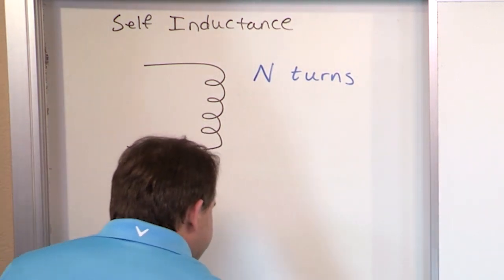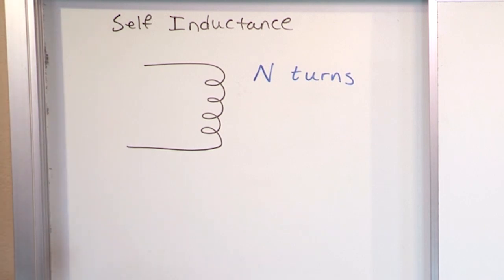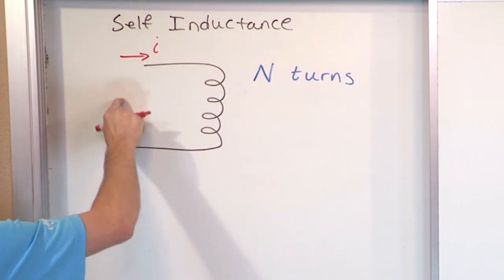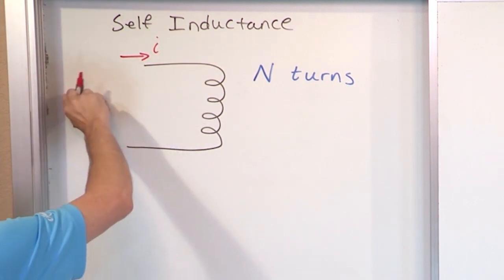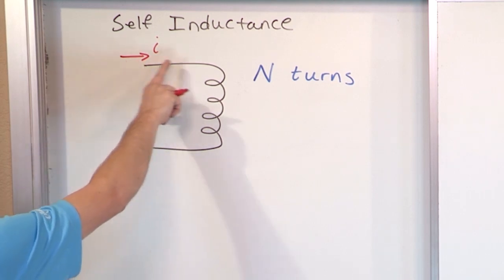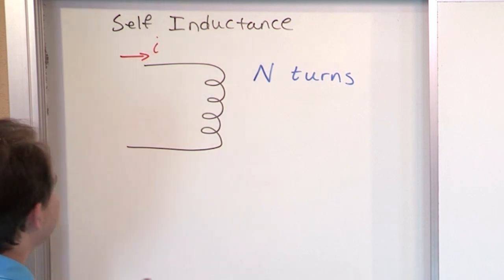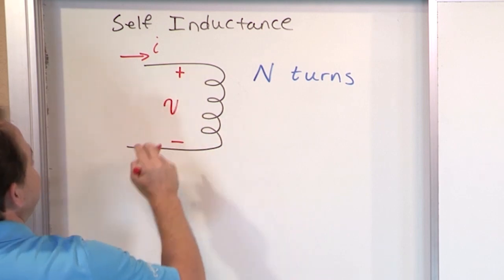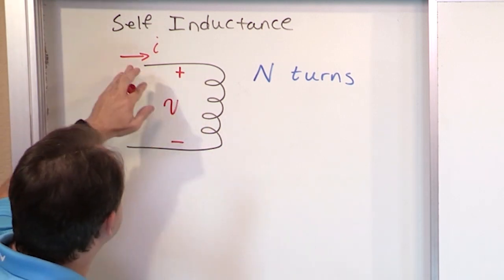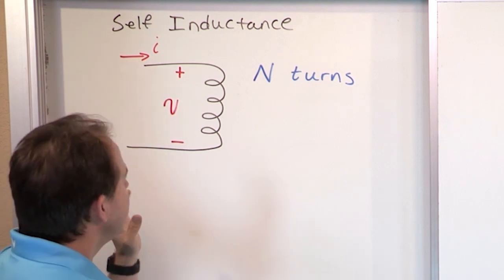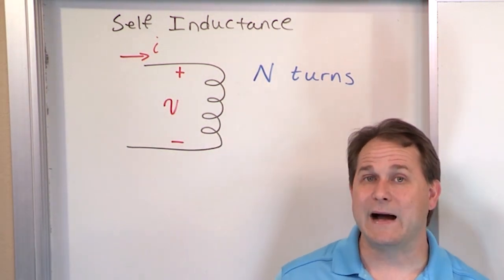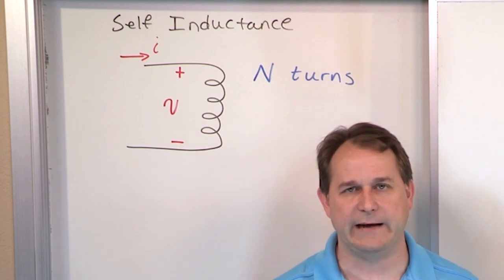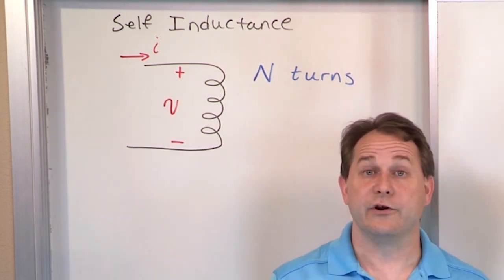If you remember the sign convention, if you go back to the very first lesson on inductors, we have current coming in here, and this could be driven by any source of any kind. It could be just an AC source, a sinusoid, or something like that. We never discussed the theory, but we said that there is a voltage drop across this inductor when the current is changing. I'm reminding you: if you have current going through that coil of wire and that current is fixed, if it's DC, if it doesn't change, then there is no voltage. It just disappears.